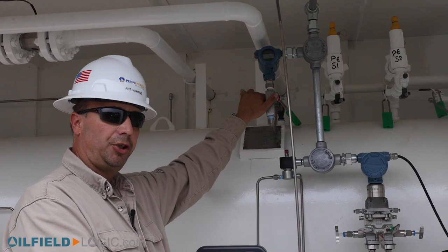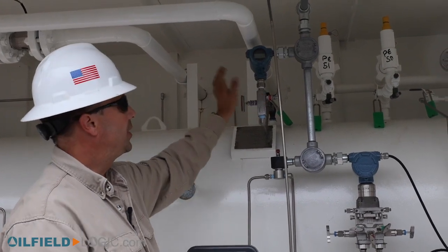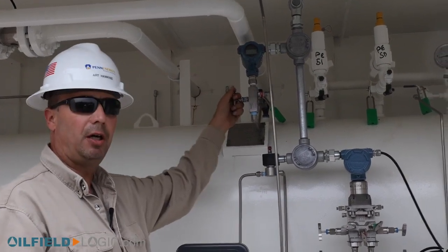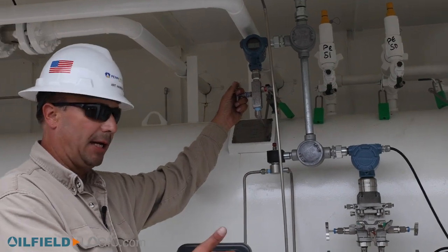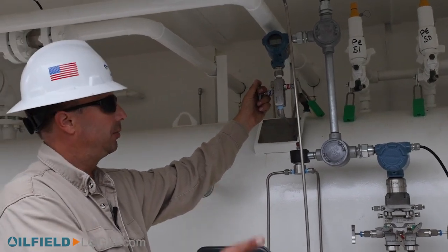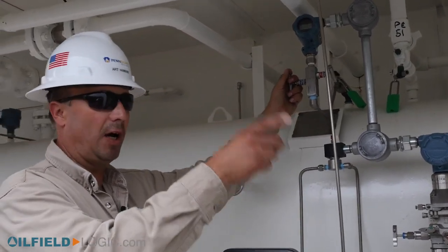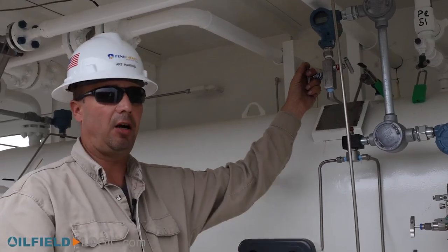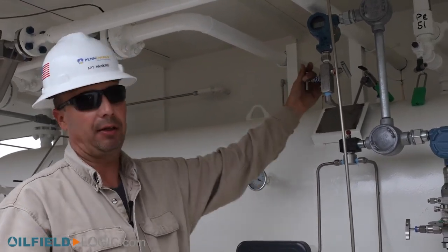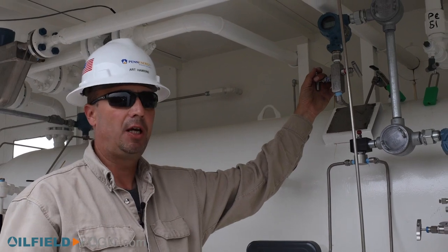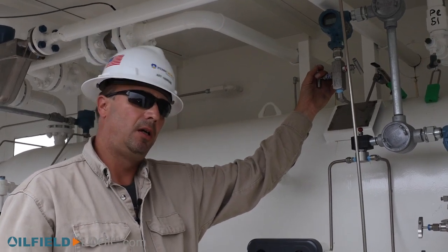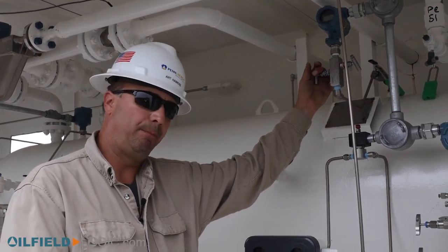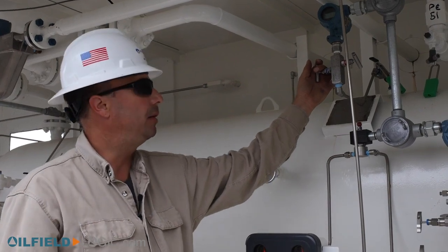Also the shutdown safety devices. If we get on high pressure, we're slipping by, a valve is leaking by, it'll protect us and shut the valve at the well. It'll shut the inlet and send an alarm to an operator. Same thing on the low side. If we have a breach, it'll protect us from a low breach to the atmosphere or in the environment.